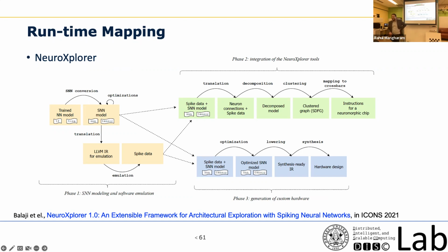Oh, really good. Okay. And do you see performance degradation, or does an FPGA degrade performance as compared to custom-built silicon? Yes, that's right. And how much of a difference does it make? A lot. So we prototype the same design on FPGA, and we put the same design on ASIC or analog design. There was a significant amount of energy-related difference. Almost 20 to 30% energy reduction we can see as compared to FPGA. So does implementing it on an FPGA actually give you anything then?